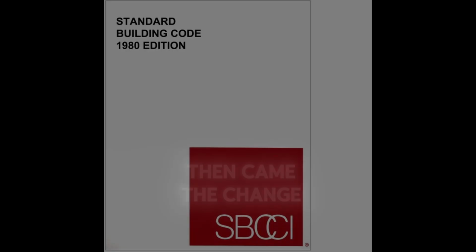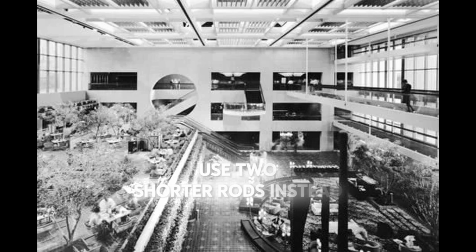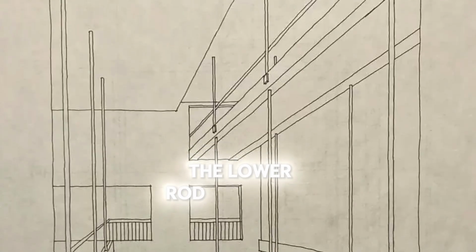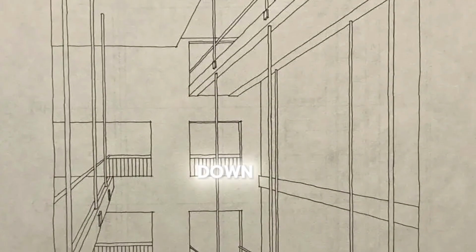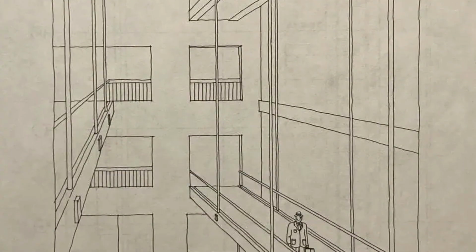Then came the change. The steel fabricator looked at the plan and saw a construction nightmare. To build it as drawn, you'd have to thread a nut up more than 20 feet of rod, over threads that would be damaged and dirtied on the way for every connection. So they proposed a simpler version: use two shorter rods instead of one long one. The upper rod runs from the roof to the fourth floor walkway. The lower rod runs from the fourth floor walkway down to the second floor walkway. That sounds like nothing. It's a fabrication convenience. It is also structurally a completely different building.